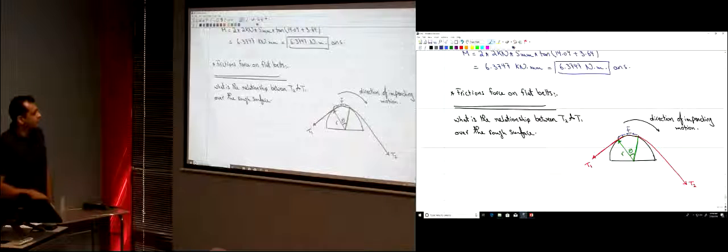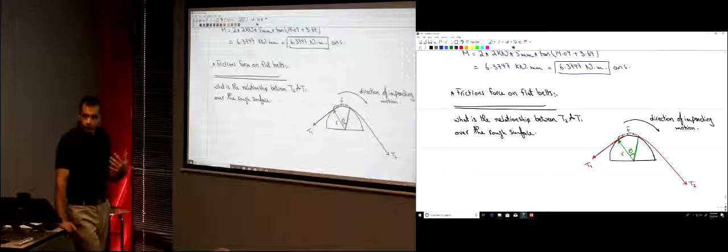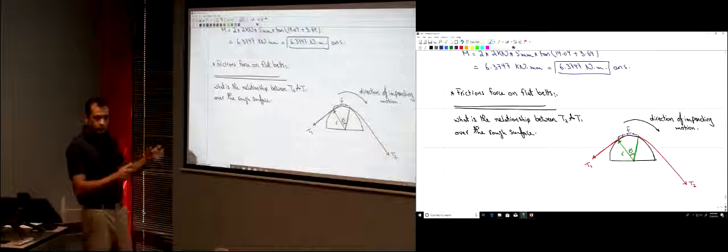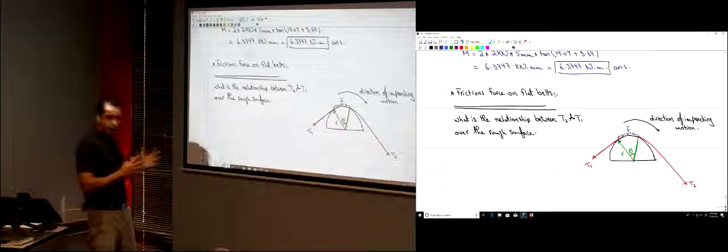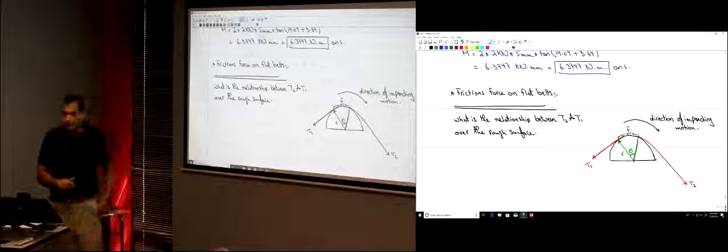So now, let's go ahead and try to understand the equilibrium here and find this relationship. We're just targeting this relationship. If we know how much T2 is, how much is T1 going to be? What do you think? Will it be larger or less than T2? T2 is larger. I'm applying T2, but the frictional force will make T1 less than T2. You're going to lose some force in this belt due to the friction.